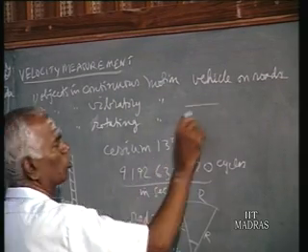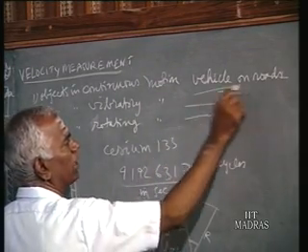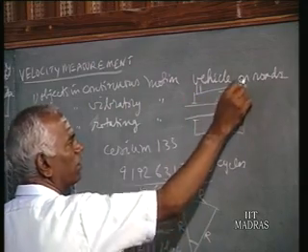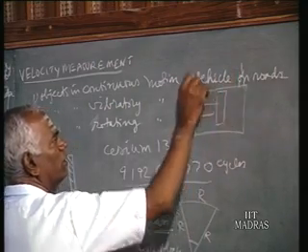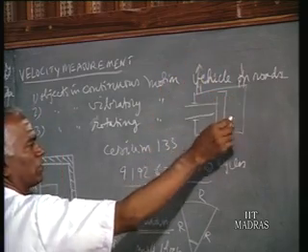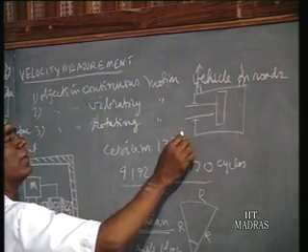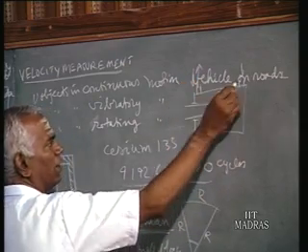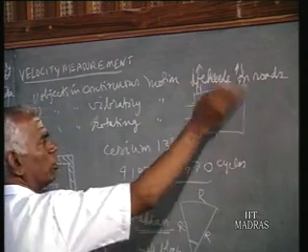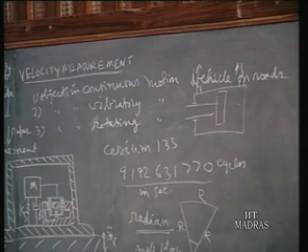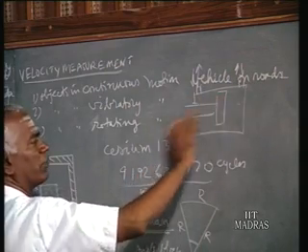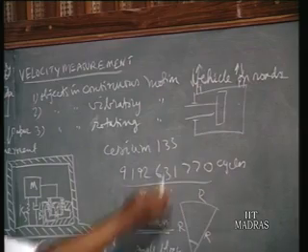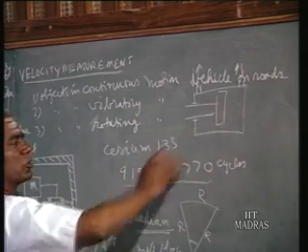For example, a piston motion inside a cylinder. So this may be a cylinder, the hydraulic cylinder. We give the pressure oil, and pressure oil goes out. When you supply pressure oil, it moves from one end to the other end. And then later on we give the supply here, and this is the output. So we switch by using a directional valve. You can switch the supply here or there, thereby making the piston move to and fro within the cylinder. That is called reciprocating motion or vibratory motion.